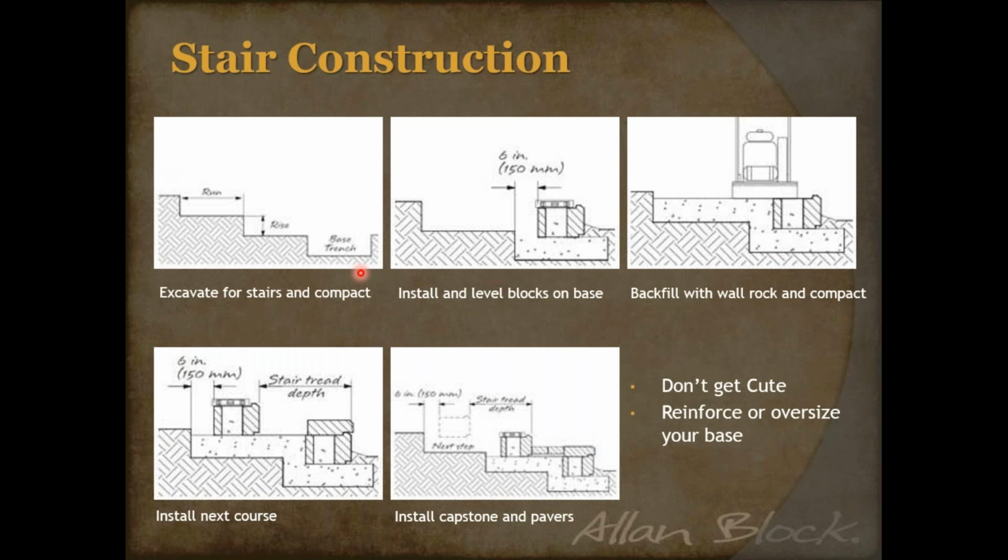You know, I'm full of a lot of sayings because I do the contractor training. I'm like, when in doubt, grid it out. I tend to put grid on just about anything out there, and that includes maybe even your base of your stairs. But then you just go ahead and make sure the block's level. You can see you need to determine where that next tread depth is going to be, because that's where your next block is going to be, and then it's just leveling that up. Obviously, using the block below it as your point of reference, so that way you can continue to make your consistent step up.